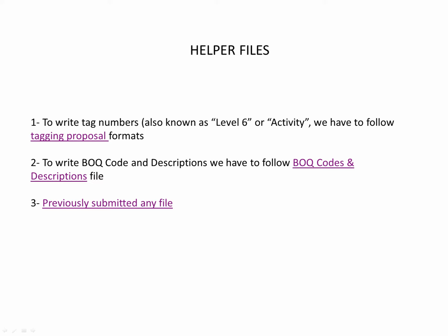But items like volume control dampers, isolation valves or butterfly valves, you tag from scratch. It's very easy, just give serial numbers from 1 till wherever it goes. But for these items you have to open engineering documents or shop drawings one by one and type them one by one. Unfortunately, this is the hard part.